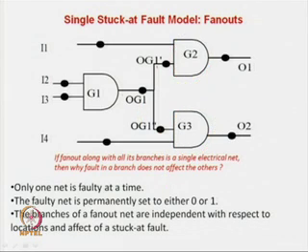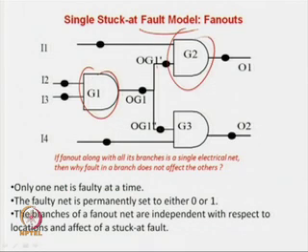So, now in this case what we have done: if you are doing structural testing, not at the functional level but at the fault model level, then what do we have to verify? We do not have to think that this is an AND gate, and so forth. We have to just verify that this line does not have a stuck at 0 and stuck at 1, this line does not have stuck at 0, stuck at 1 and so forth.